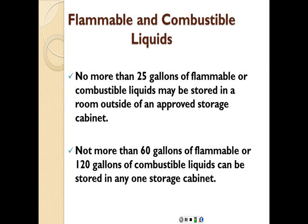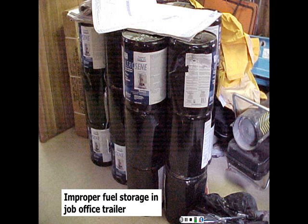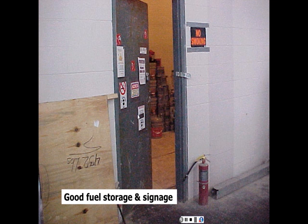Now, which one is easier to ignite, the flammable or the combustible? Obviously, the flammable. That's why we have a lower limit. So here, for example, we have improper fuel storage in a job office trailer. First of all, it's close to a heat source, not proper containers, stacked improperly, and the amount is not inside a cabinet as we just mentioned. Here we have them inside a room, and we have a no smoking sign, we have the fire extinguisher, we have a fire rated door, and we have all signs of warning on that door.